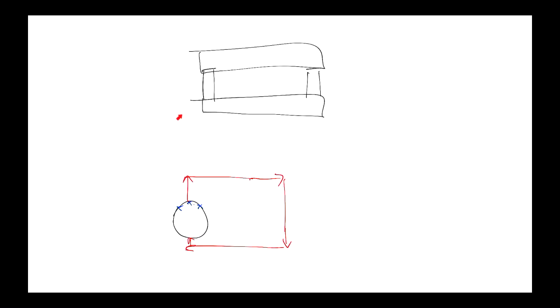And then after some distance, which can produce a reaction because you can measure the distance travelled by the robot, perhaps execute another turn and then go forwards. So you're probably looking at maybe 5 or 6 states in order to run into something, cause a reaction in the state machine via the sensors, and then execute a series of alternating turns, one way or the other, and end up going the same direction around it.